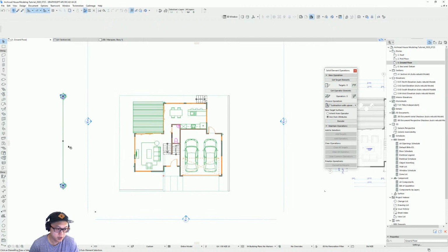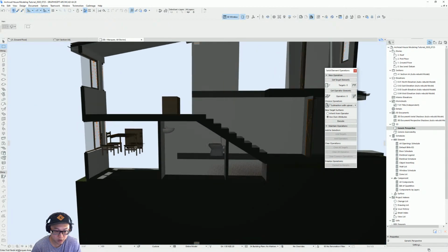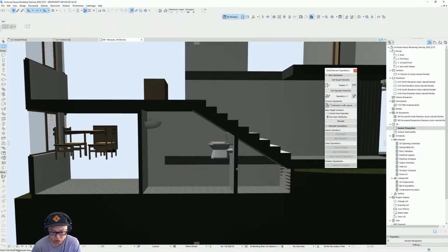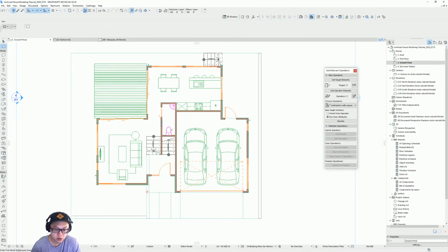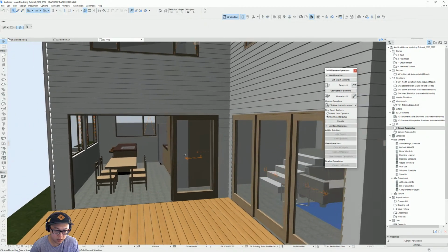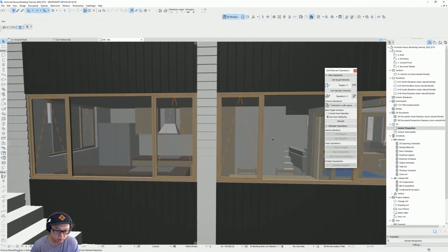If we were to bring back a section here, or even we can just do like I did before, but this time we're going to use the black one because I want to see the other stories above. 5. And oh, we need to move down all our stuff, but you can see there's a staircase. Well, actually it shouldn't be a problem, you'll be seating anyway. But let's move everything down 900. Just gonna select all of those and type minus 900. Now everything should be on the same level. Yeah, it's good for now.